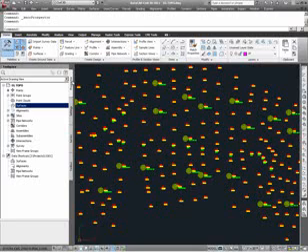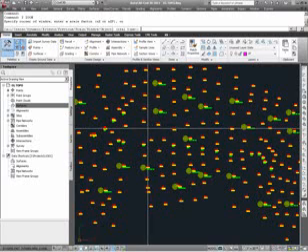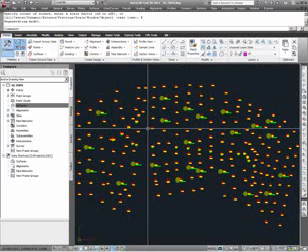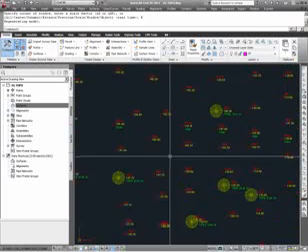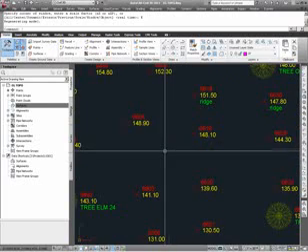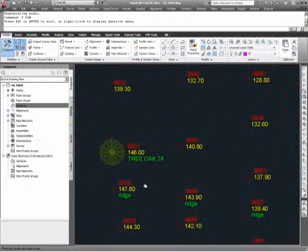Once the Prospector view is shown, we now see through tool space that we have access to the drawing and its surface contents. Looking here, we find that there are no surfaces in this drawing. As we begin to create a surface, let's take note of what we have in this drawing called EG Topo. As I zoom extents, I see what appear to be Civil 3D points, and in zooming in, I do verify that they are in fact Civil 3D points.